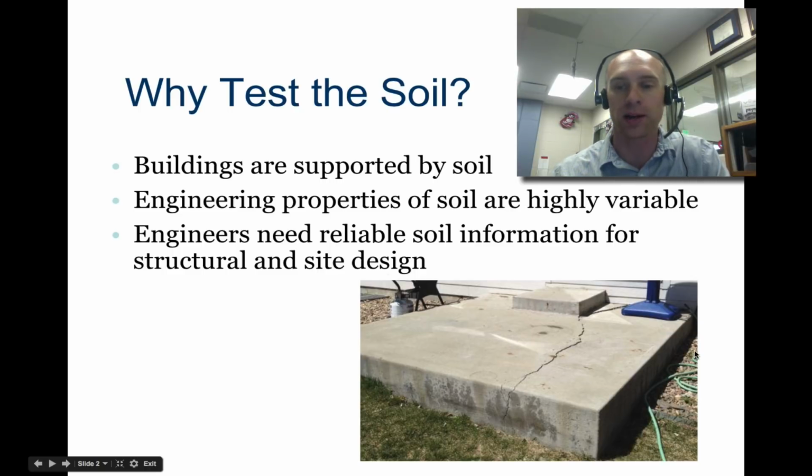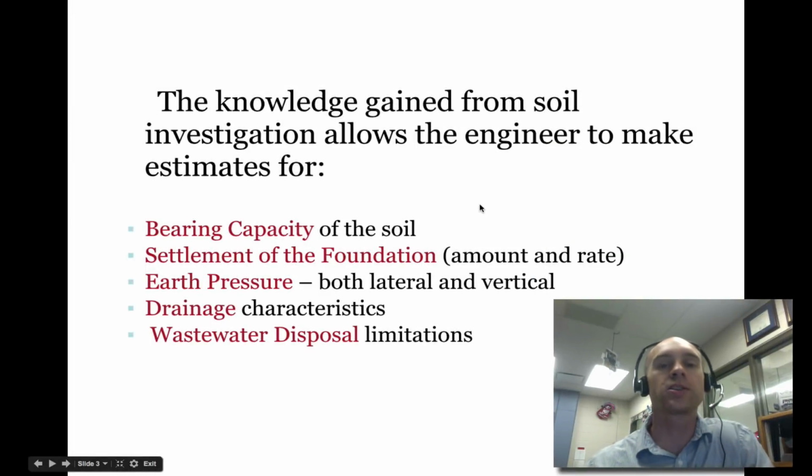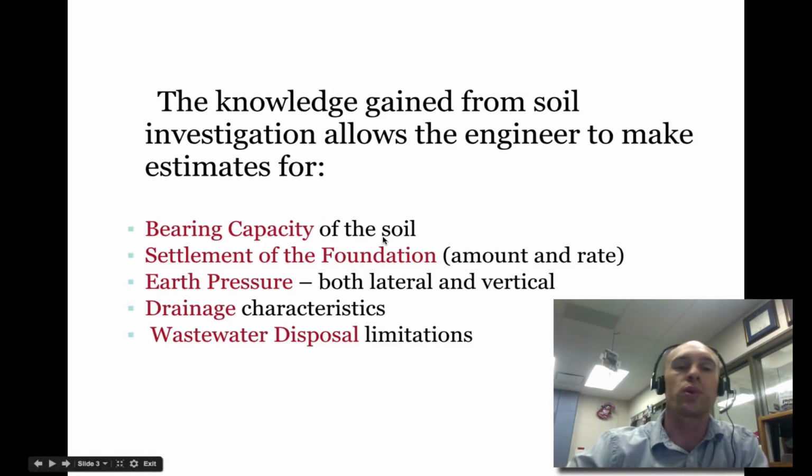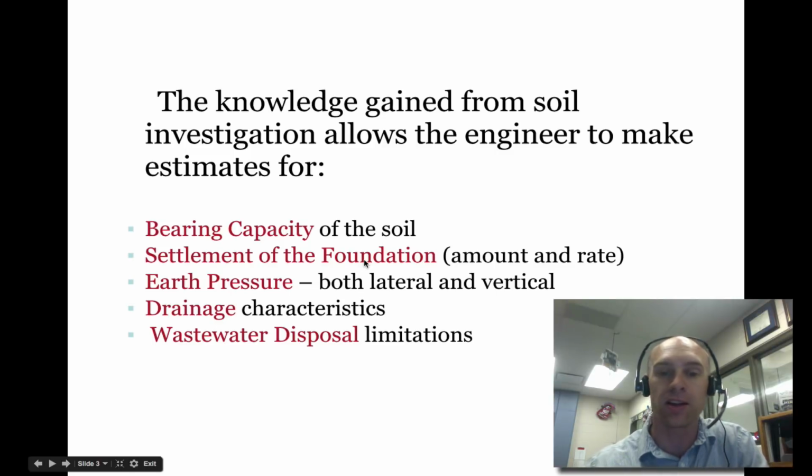So if the soils were not compacted here, which likely they were not because this is not a structural piece, then slowly they'll sink and sag, and then, sad for me, I had a broken concrete slab. So, knowledge gained from soils investigations allows engineers to make estimates for bearing capacity of the soil. How much load can you put on that? How much it's going to settle that foundation?